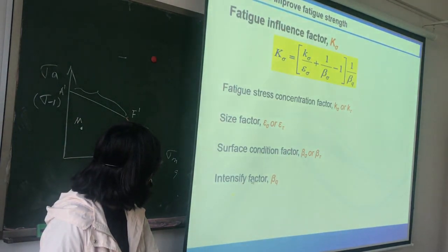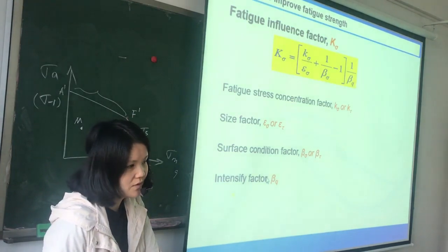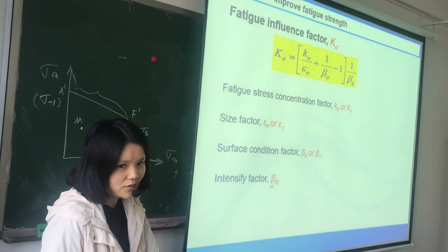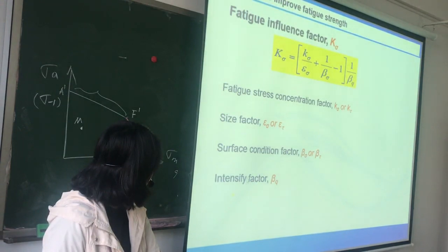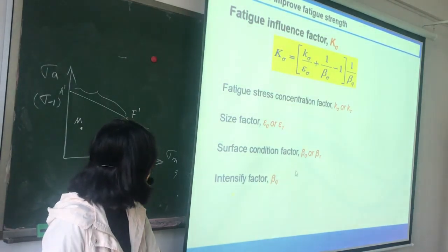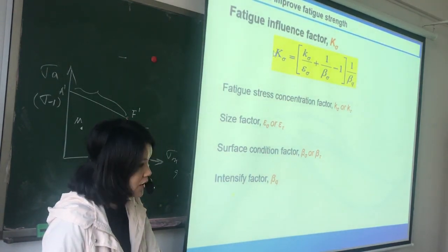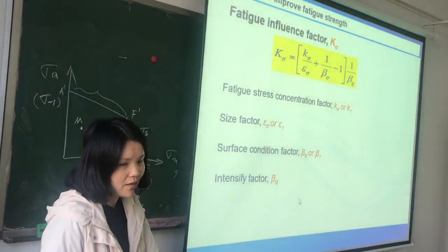And this is the intensifying factor, which considers the surface treatment, like surface cold rolling. Any surface treatment will increase this factor, so it decreases the fatigue influence factor, and can increase the fatigue strength of the element.